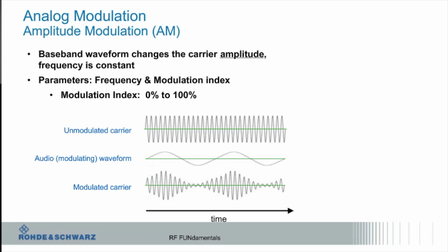And what does it look like? For amplitude modulation, the third line, you can see that high frequency signal getting smaller and bigger and smaller and bigger. The change in the amplitude of the high frequency carrier is the information. That's what we're going to transmit through whatever medium, using an antenna or whatever, and then take that off on the other side.